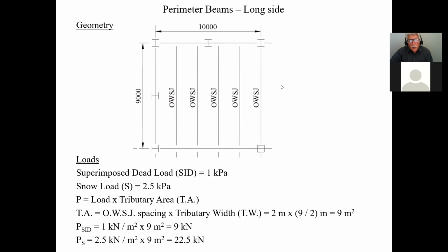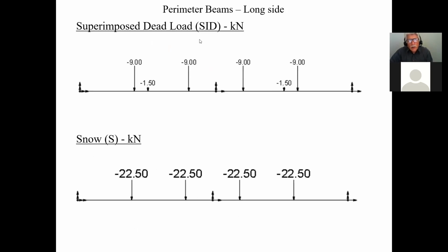Okay, now, once I did that, of course, now here is all I did here. And guys, I do suggest you do this, okay? This is where that sag rod was going to come down and support that girt and then support the other girt and so on. So I just put 1.5 kilonewtons here, okay? And I'm sure I've overestimated the weight of those girts, but I'd rather be on the safe side, and therefore this is just an assumed value.